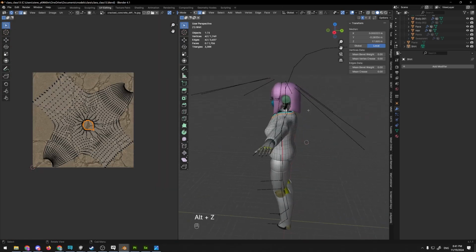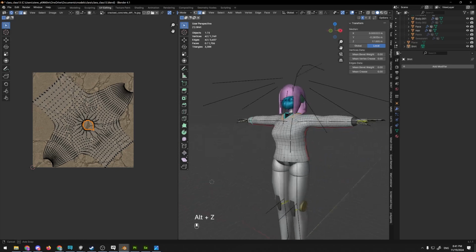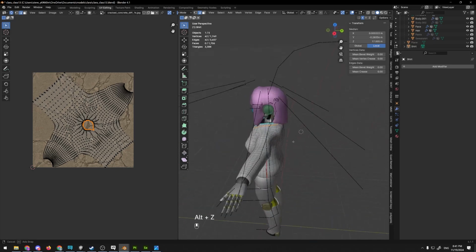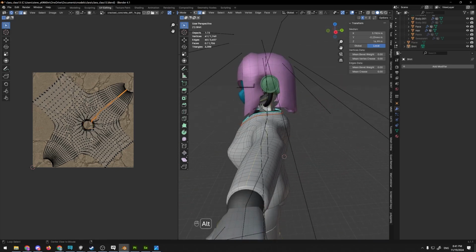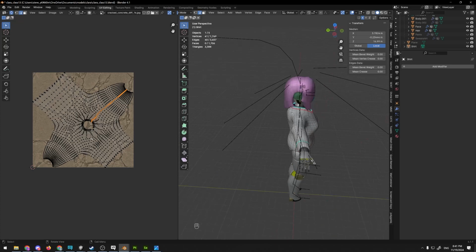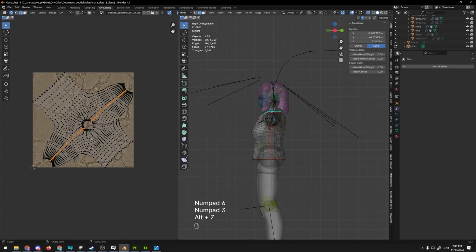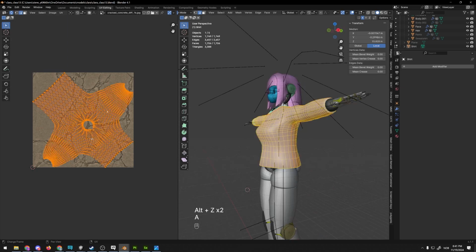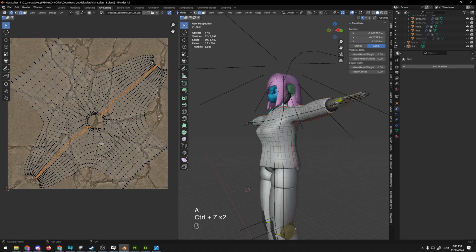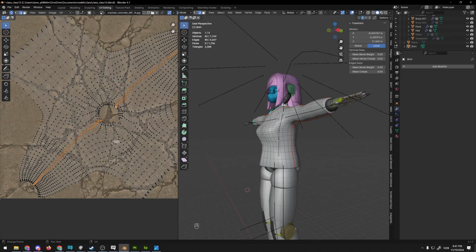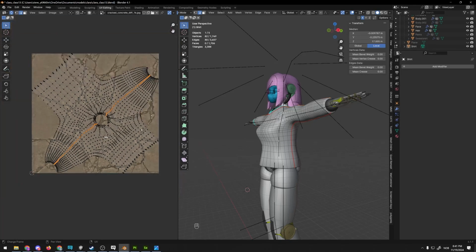And now to kind of split the shirt in half from the front and from the back, we're gonna add a seam along the top of the sleeves as well. So seam there, seam here. So those line up. We can check our orthogonal view to be sure. Yes, they do. And now if we unwrap, we can actually see why on our UV view over here on the left, why adding a seam here will work. It splits it in half. We can see we cleanly have our back half and our front half here.